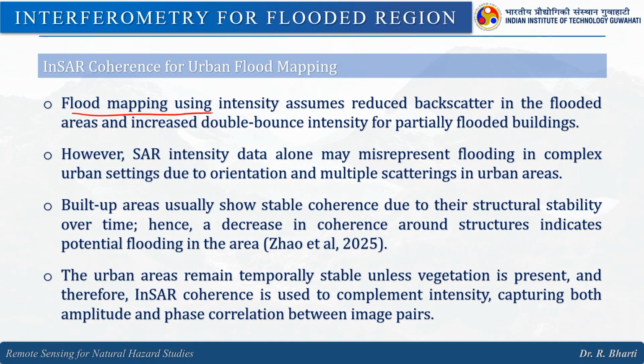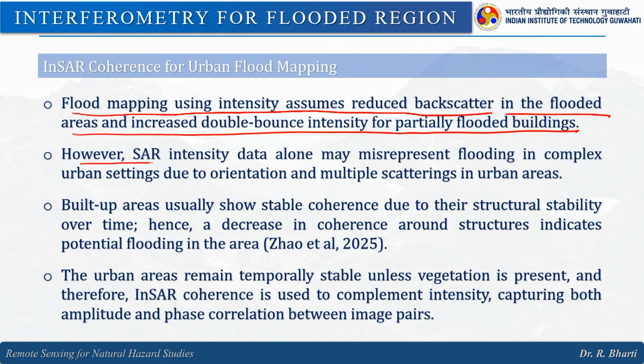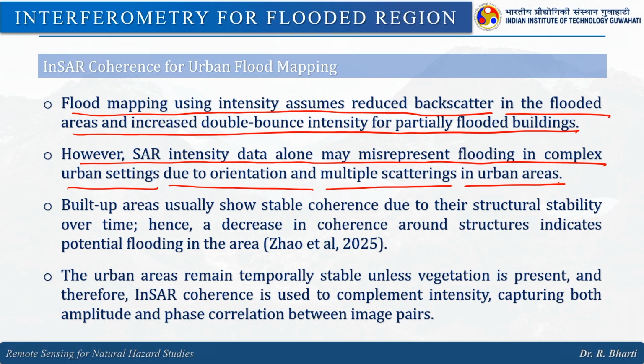Flood mapping using intensity assumes reduced backscatter in the flooded areas and increased double bounce intensity for partially flooded buildings. However, SAR intensity data alone may misrepresent flooding in complex urban settings because of the scattering mechanism due to orientation and multiple scattering in urban areas.